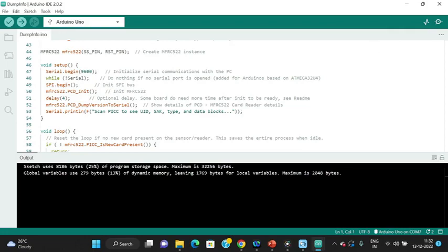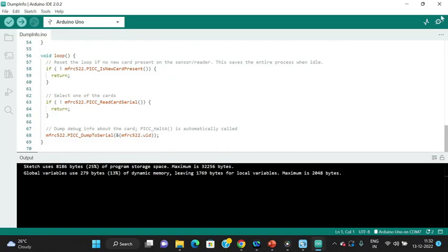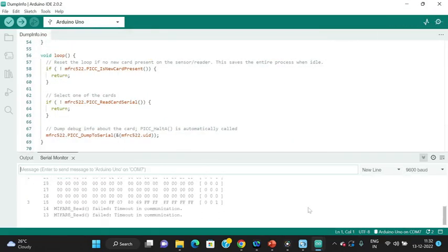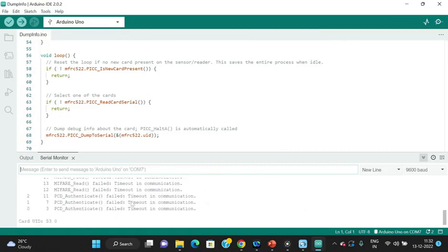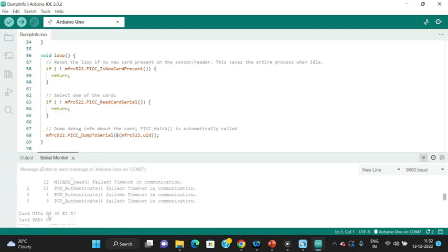There is some technical glitch in the Arduino IDE, but yes, go to the serial monitor and put the card in front of the RFID reader so that it will pick up the RFID card number. In this case, the one that is highlighted is the RFID card number. Note down this number, as we need it added to the main code.